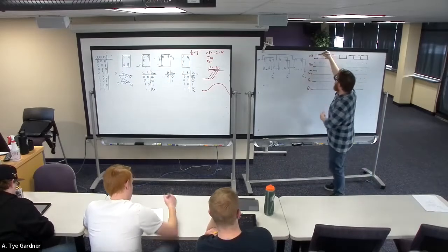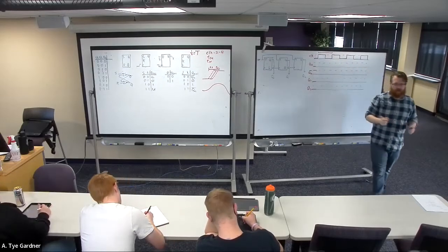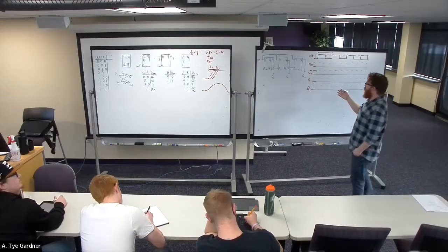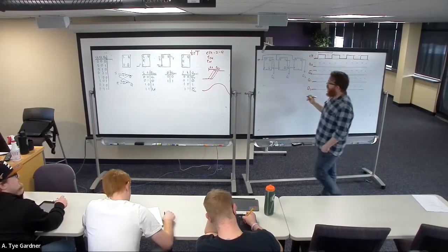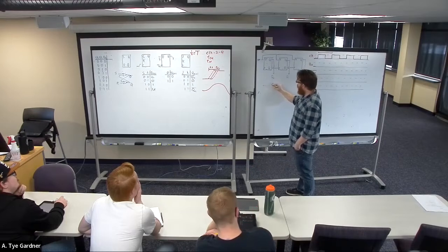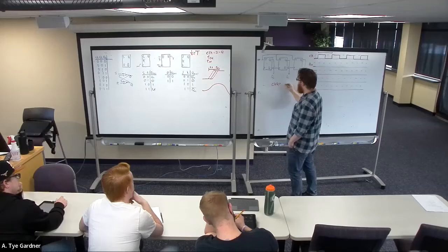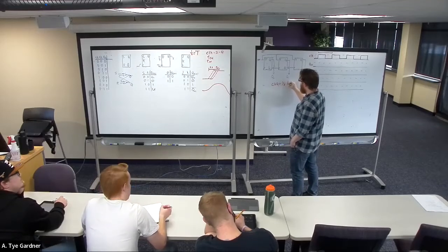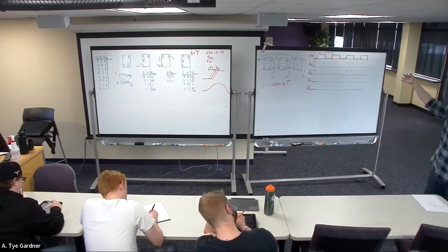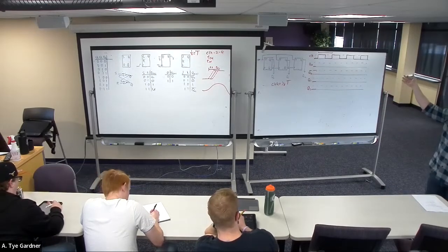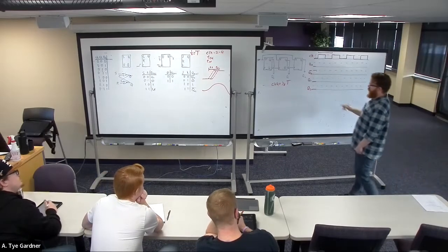So in this case, from here to here is the period. So let's assume that there's some amount of clock to Q delay in this circuit. And in fact, I'm going to define the clock to Q, C2Q, is going to be 1/8 of a period. So this is just abstracting away, so I don't have to write exact times up here, whether or not this is a 20 nanosecond period or a 100 nanosecond period. We're just going to talk about it in terms of the ratio.